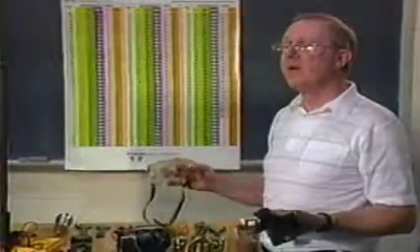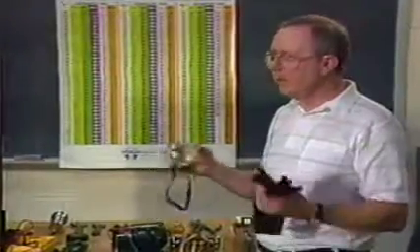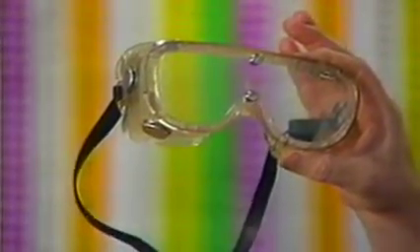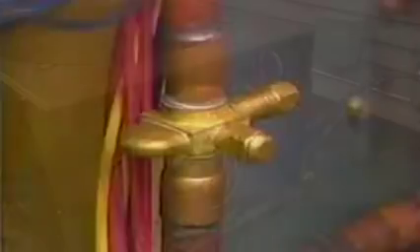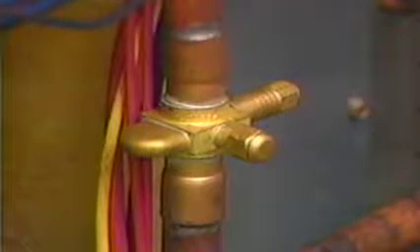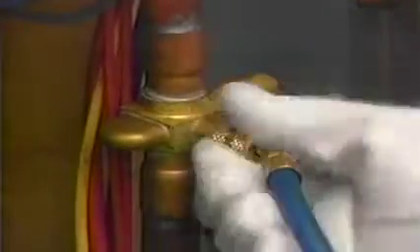In the vapor state, you will not be able to burn yourself, but you would be subject to blowing debris in your eyes, so you would always want to wear goggles while handling or transferring refrigerant in the vapor state. Two types of pressure connections are used, the Schrader valve and the service valve. The Schrader valve is a pressure connection only. The service valve can be used to isolate the system for service. The system might have a Schrader connection for the gauge port and a service valve for isolation.